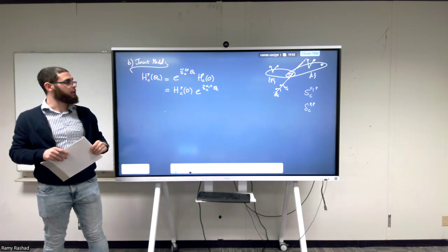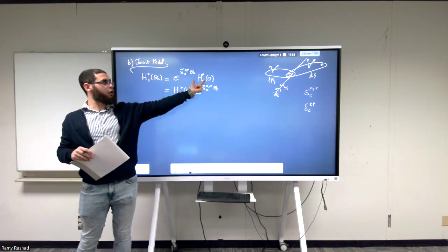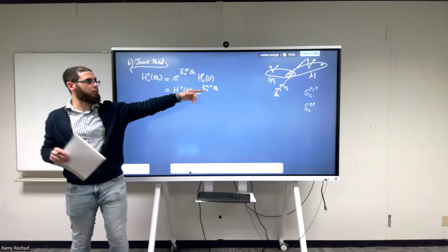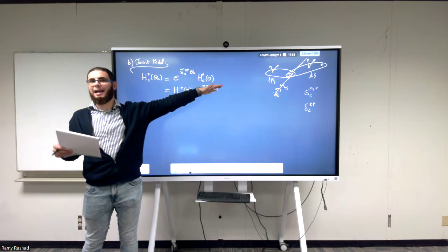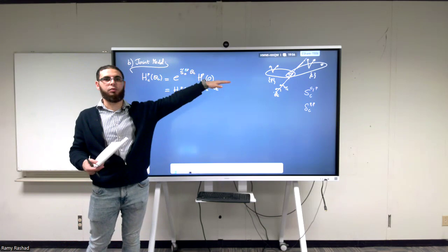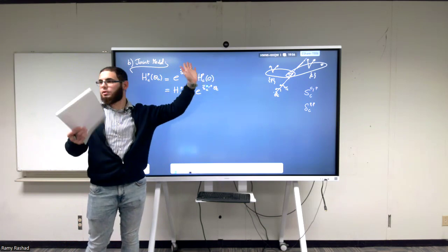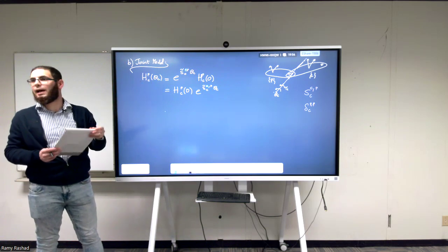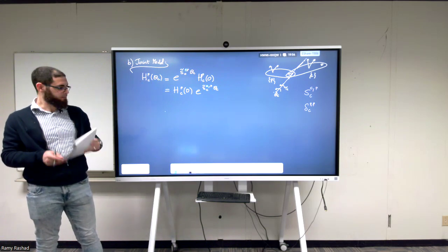It's something very easy. And you just give it the constant transformation at angle 0, which is something that you choose. What is the angle 0? What is the home configuration? What is the angle at which these two are aligned or not aligned? It's up to you. It's your choice. And then for any given angle, you can calculate the relative pose like that.